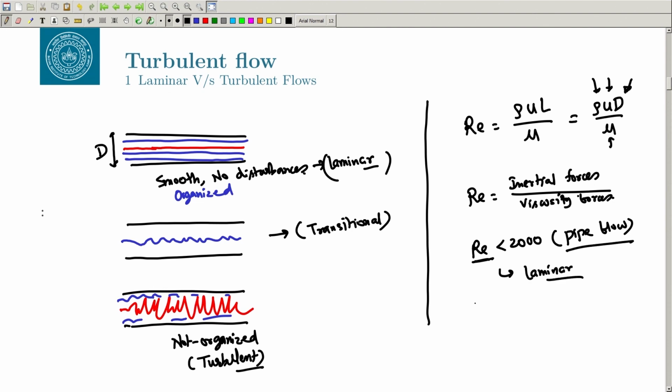Okay. And then when the Reynolds number was greater than 4000, for the same flow, he observed the flow was becoming turbulent, right. So, remember this 2000 and 4000 is not a sacrosanct number; it can change if you can make the environment very quiet. So, let us say that you can make the pipe completely smooth, there is no friction there, and the environment is also very quiet, then it can increase this number to a very high value. There are super pipe experiments in Princeton where they have observed that they can maintain the flow to be laminar to a very high Reynolds number.